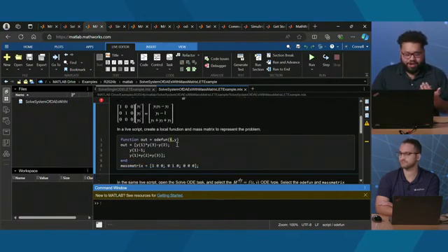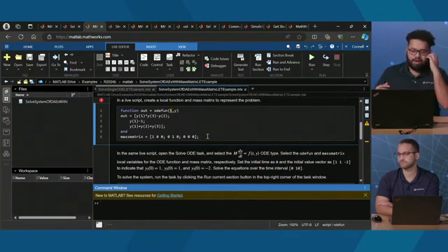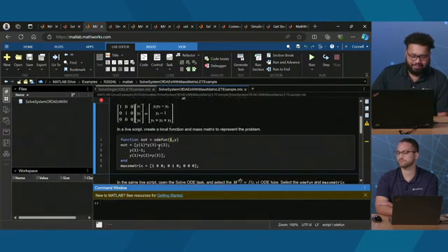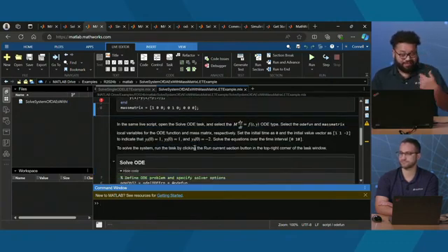The first thing that you have to do when you're using this Solve ODE live task is essentially create a function of the ODE, right? So you create a function and then you pass that function handle to the live task. All that we're doing here is taking this right hand side matrix and representing it as MATLAB code. And then we're also creating a new variable called mass matrix, which is essentially the mass matrix on the left hand side, right?